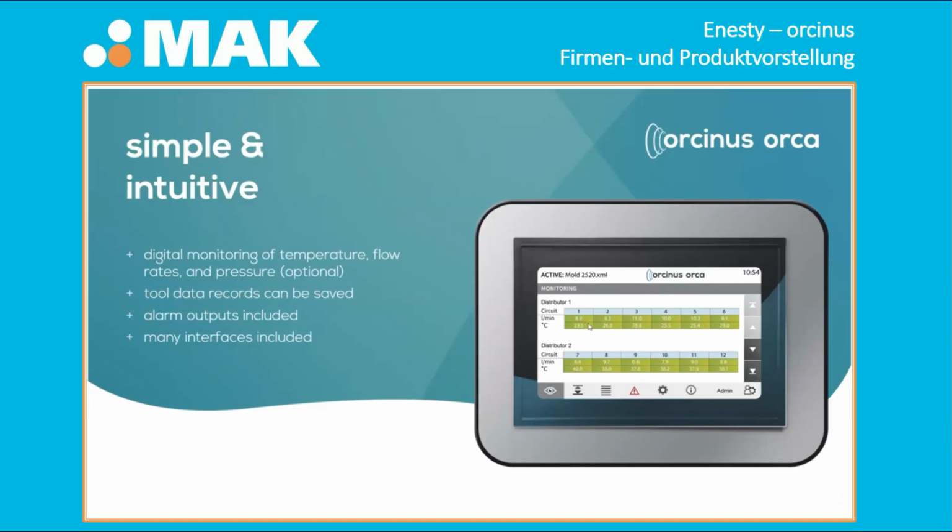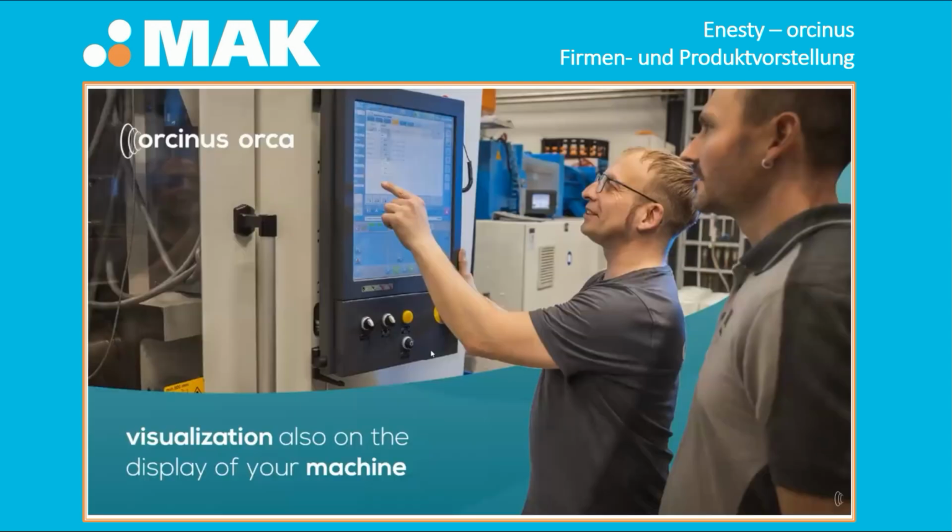And when you're looking inside your mold and you can see every single circuit's temperature and flow, you can see what's possible. So you can play a bit with this. And this is how you can shorten your cycle time as well. Because when you realize, oh, in this circuit there's 8.9, but it should be 20, you know something's missing. So you can look for the reasons. And when you fix this problem, then you might have a much smaller cooling time.